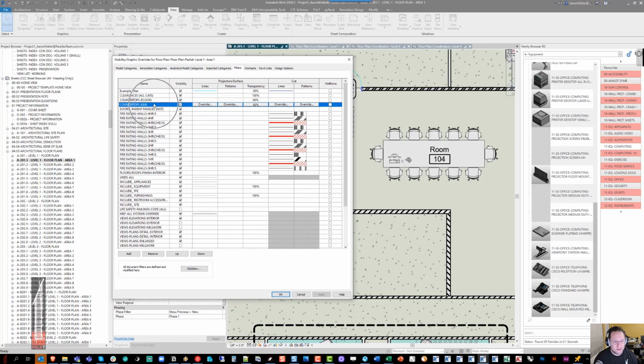There are also two filters, one that is looking at the floors category and one that is looking at generic model families, both looking for an abbreviation that stands for countertops. The purpose of this filter is to set the countertops to 60% transparent as a way to enable us to see base cabinets in plan. A lot of content libraries do base cabinets with symbolic line work, but this means that base cabinets can actually show their model geometry, which suddenly gives us control, allowing us to not show base cabinets at 16th inch, but then show them at 1/8, 1/4.